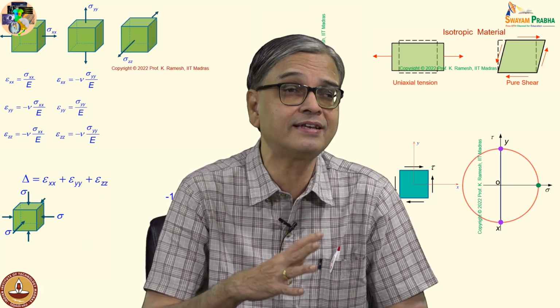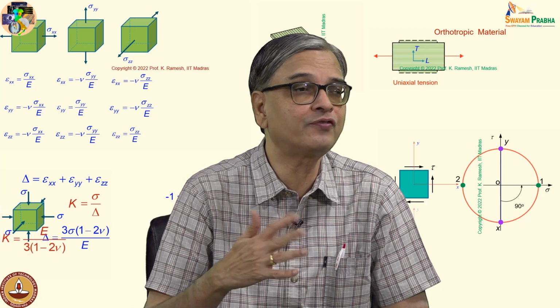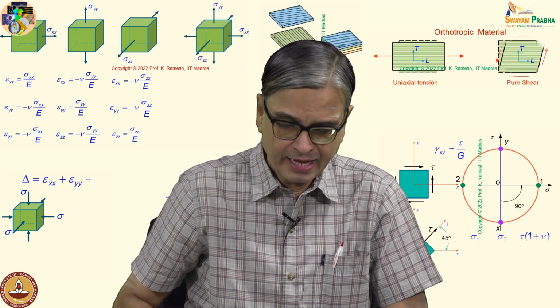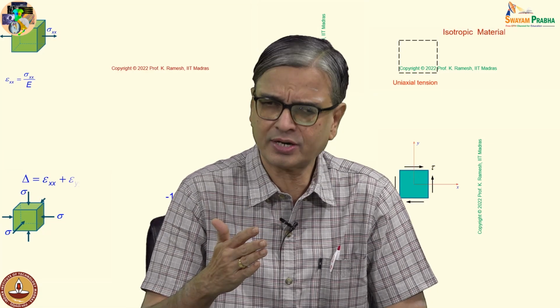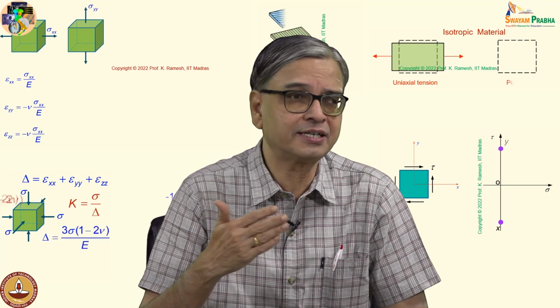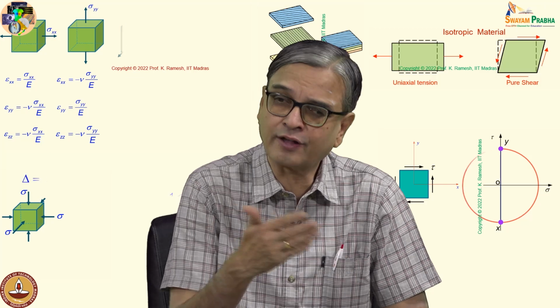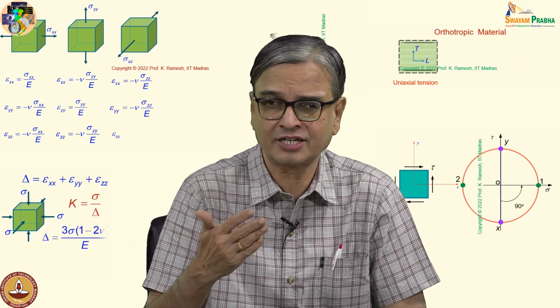How does the material behave under the application of different types of loading? So that is what we are aiming at. And we have looked at a very important aspect. When we conducted the tension test, we also saw material separation. That is also important, because once you understand that every component may have inherent defects, these defects can grow during service and you can have fracture. Such failures have happened.